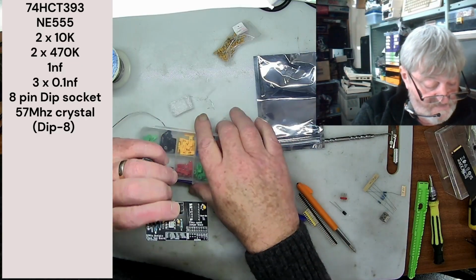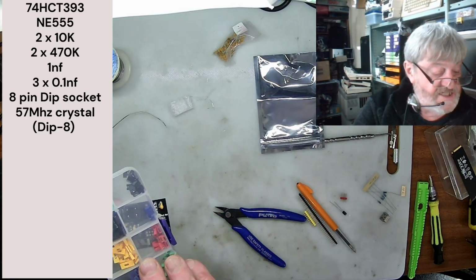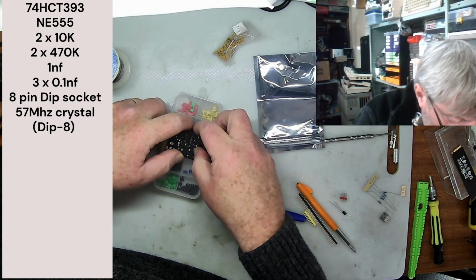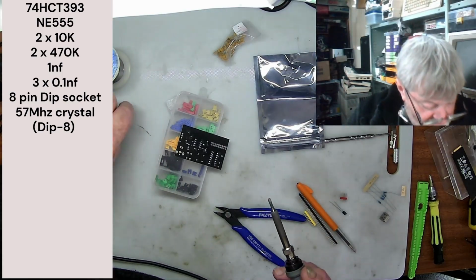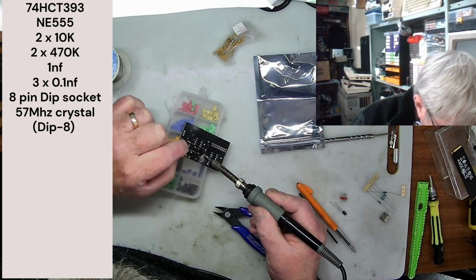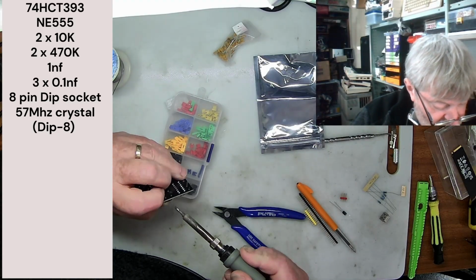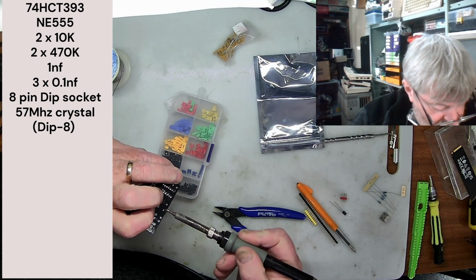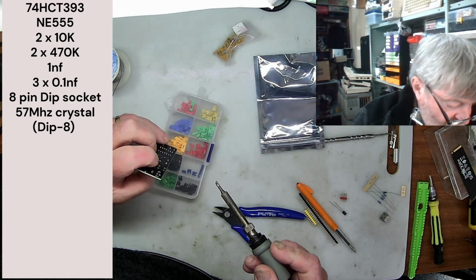So same thing. I find something like one of these is really handy, because you can just sit it on the top to hold it there while you turn it over. And then you can just tack 1 or 2 sides and make sure it's square. Solder it in. Cool. Got one side. See, it's not sitting down flat, so we'll push it down. Tack that side. Yep, that's pretty good.